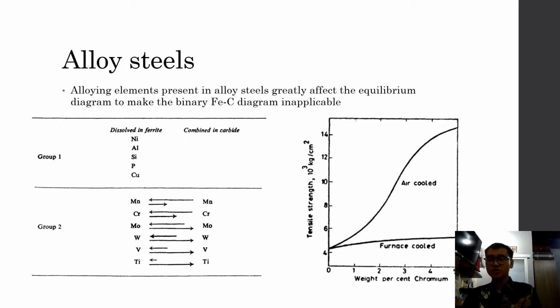Different alloying materials will have a different effect on the produced alloy steels. Manganese contributes largely to strength and hardness and has a moderate effect on hardenability. Nickel improves toughness of pearlitic ferritic steels, heat resistance, and corrosion resistance. Chromium improves strength and toughness in low carbon, and improves hardness and wear resistance in high carbon. A nickel-chromium combination increases toughness and wear resistance.